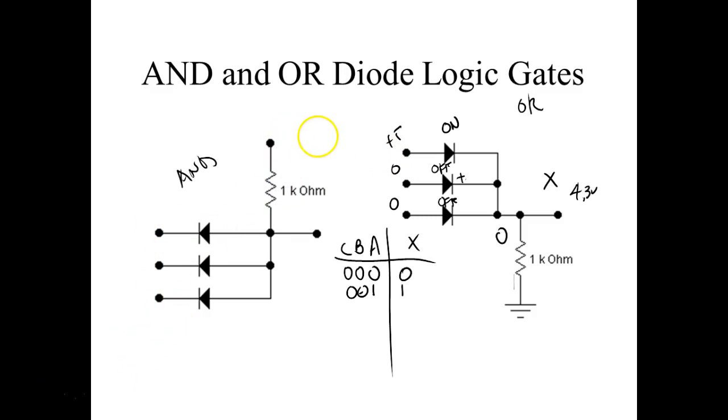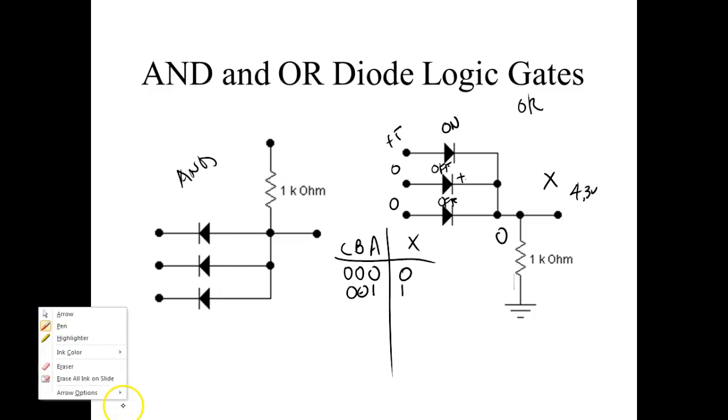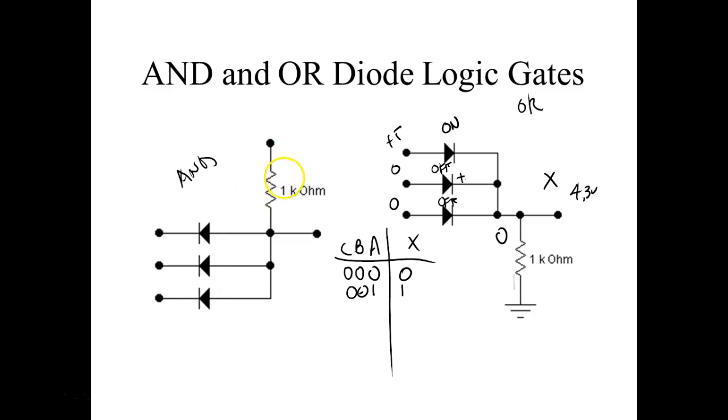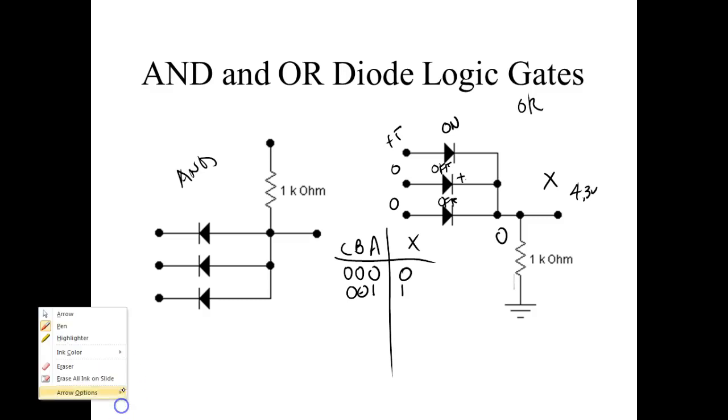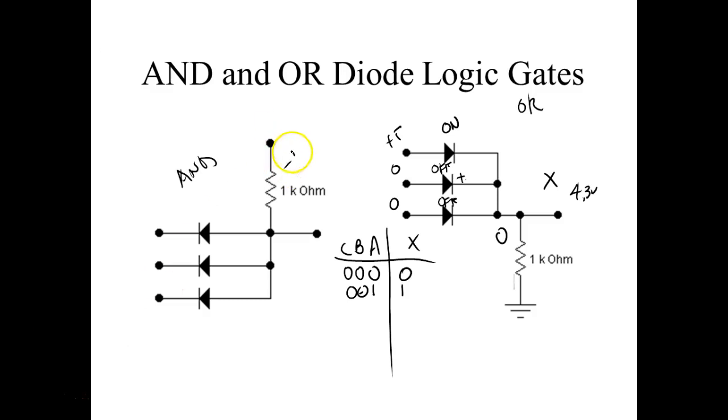by the way, technically we call this a pull-up resistor. Call it a pull-up resistor. Because over here on this left side, that resistor is providing the high. Right? You understand? My diodes are not providing the high because when I put 5 volts, they turn off, right? So technically, what we call a pull-up resistor. And what do you think we call this one? Pull down, good.